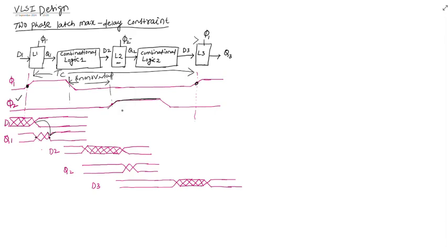Now we'll understand what the delay will be here. I have given the data D1 to the L1 latch. When the rising edge and the positive level, that is 1, comes in the clock signal, the data D1 will be transferred to output Q1, which you can see here.